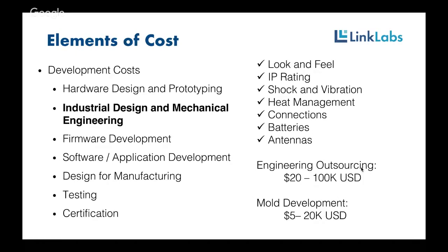So that kind of brings you into the lithium realm, where you've got lithium polymer rechargeable batteries and primary batteries, but they're limited on the amount of pulse current they can supply, and then you need capacitors. So it's pretty complex, and you can pay anywhere from pennies to many dollars for batteries, depending on the chemistry, the form factor, availability, and safety ratings. Really complex portion.